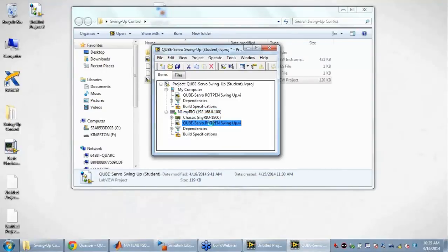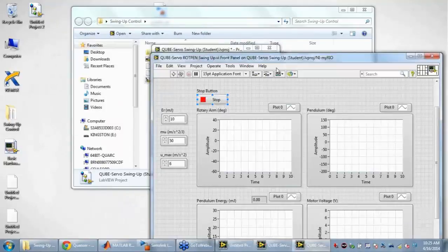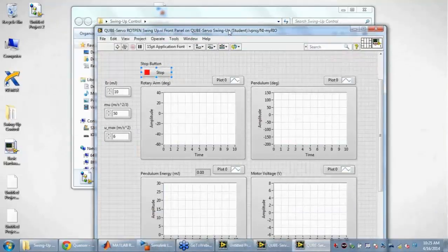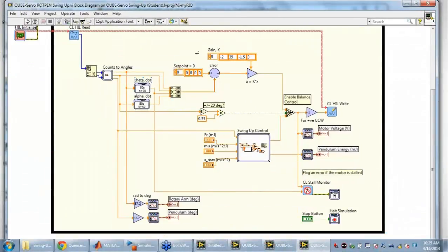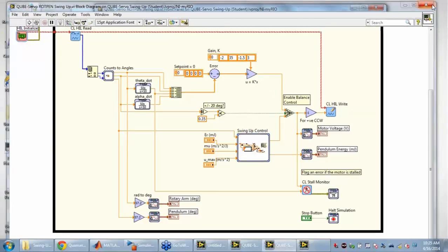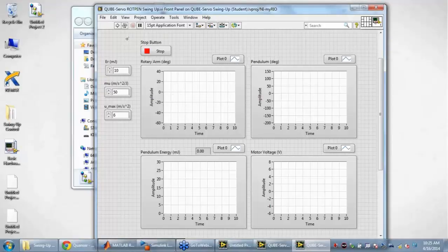This VI is basically just running a controller. You can see it's a little bit more complicated, but basically what it's doing is just taking in our state of the pendulum system, running it through a state feedback gain that we derived in some other labs. And then in parallel to that, as a sort of a hybrid control scheme, we have our Swing Up controller, which is trying to bring the energy of the pendulum to the point where it inverts, just using a simple algorithm that's more or less like a proportional controller.